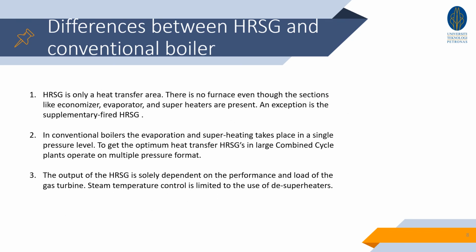There are differences between HRSG and conventional boiler. First, HRSG is only a heat transfer area. There is no furnace, even though the sections like economizer, evaporator, and superheater are present. This is an exception for supplementary fired HRSG.